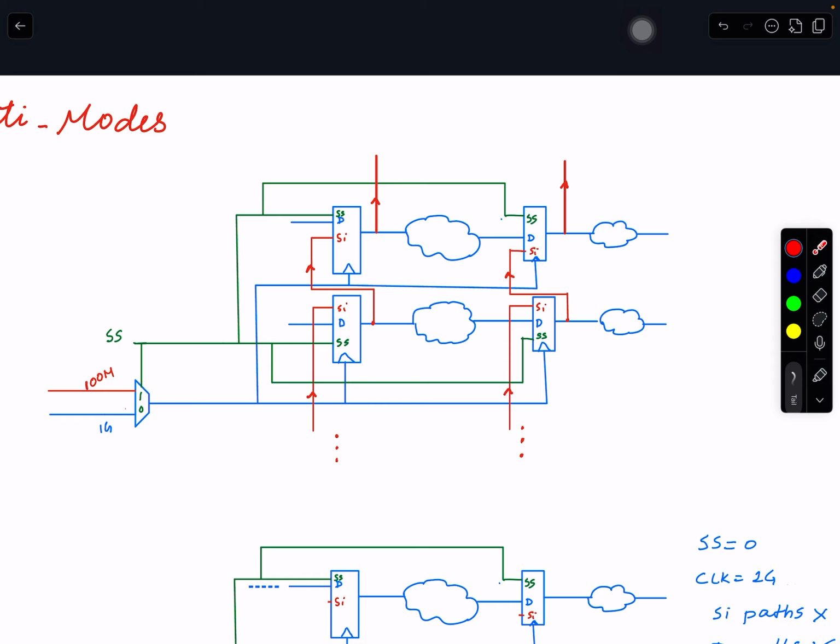So what is the tool going to do? The tool is going to time all these 3 input timing paths on both clocks. And from the input through the output, it is also going to create 2 timing paths, this and this, on 2 clocks. So you will have 4 paths here, and you will have 6 paths on the input side. Okay, that's fine.